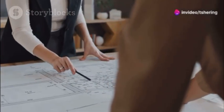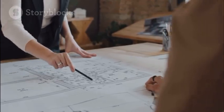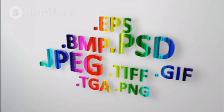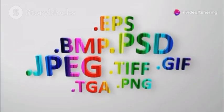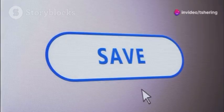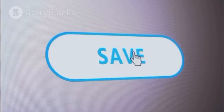But what if you need to share your drawings with someone who doesn't have AutoCAD? That's where exporting comes in. AutoCAD lets you export your drawings in a variety of formats, including PDF, DWF, and even image files like JPEG and PNG. To export your drawing, click the Export button, choose your desired format, and you're good to go.